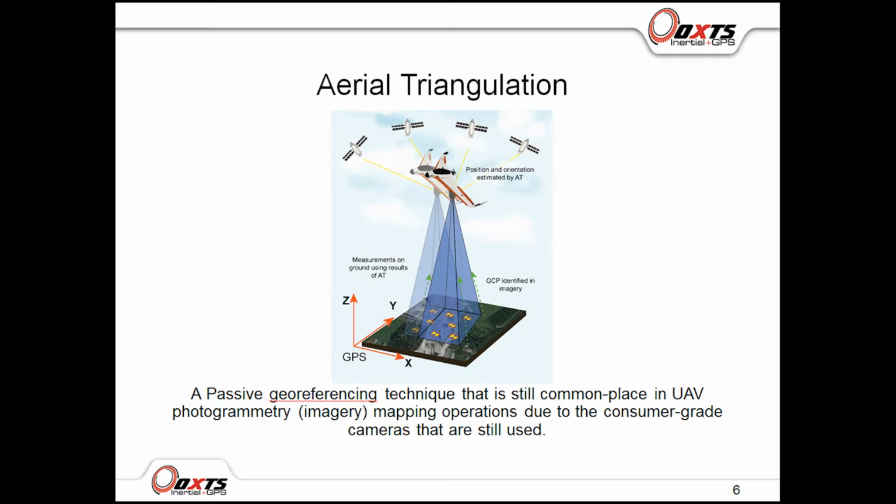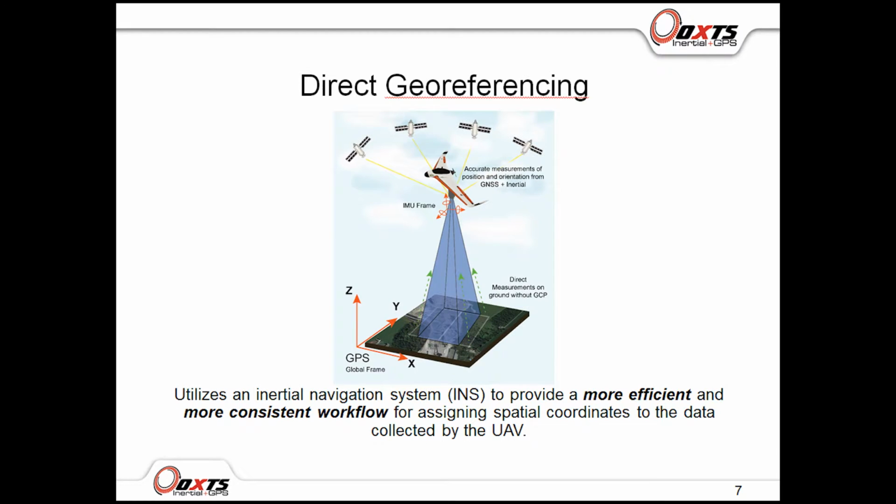With the increased use of UAVs for mapping purposes, and with it the miniaturization and development of specialist sensors for mounting on these UAVs, the efficiencies brought by direct georeferencing workflows are also being recognised in the UAV community too. So given that a UAV's flight controller system might already include a GPS sensor and an IMU, one question that you might be asking is why a separate INS system is needed in the first place.